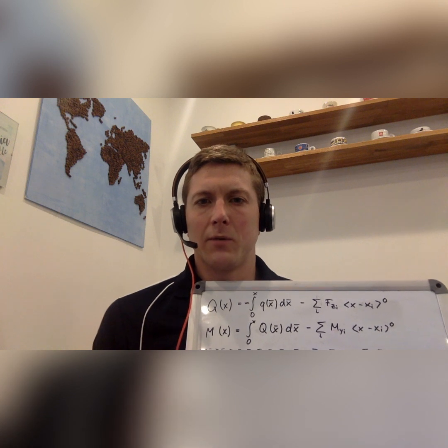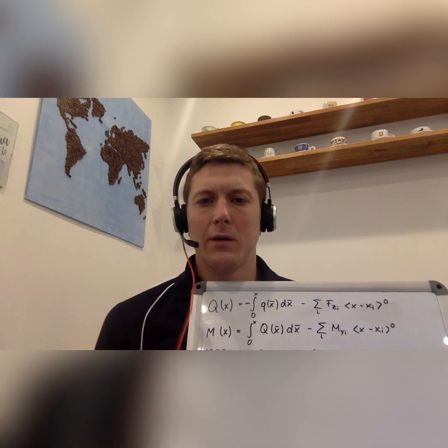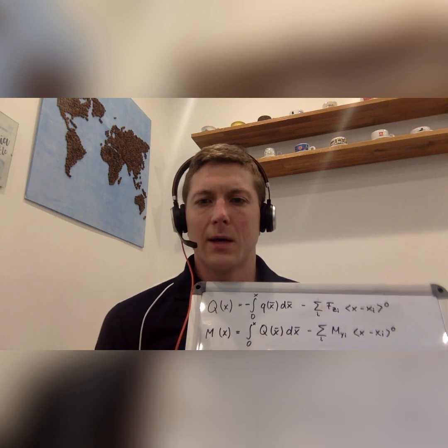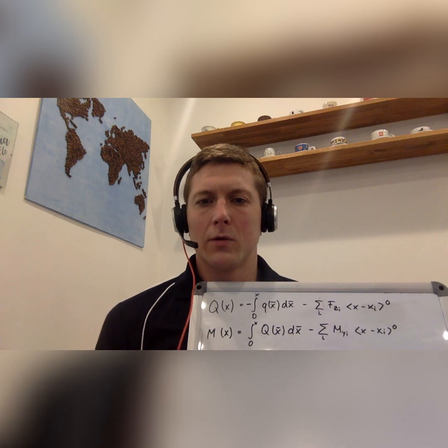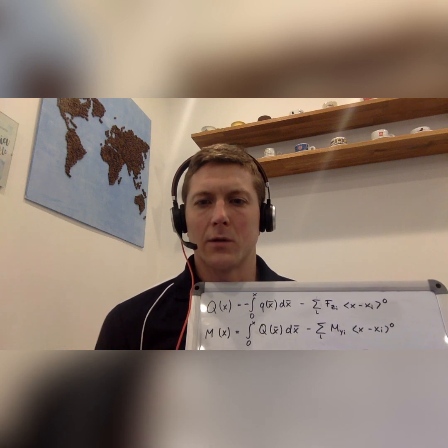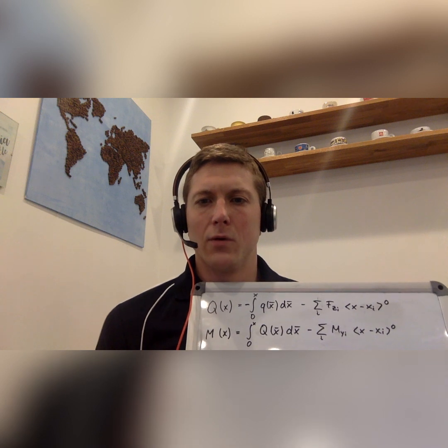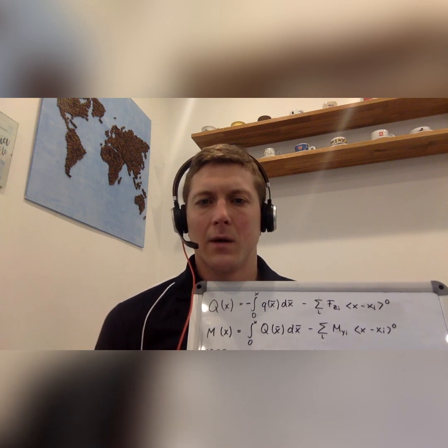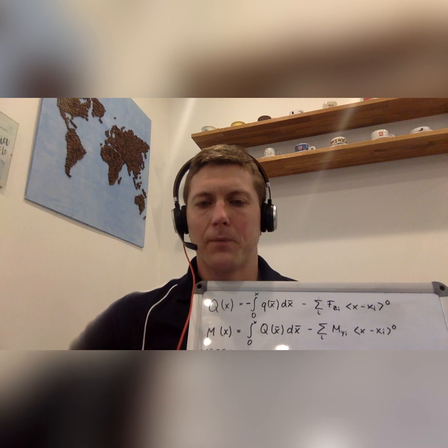And then you would have, of course, the same way to calculate the shear force and the bending moment. So there are two different possibilities, either the definite integration scheme, which is given here. That is the reason why I use this x bar instead of x for the integration variable, or you could choose an indefinite integration, so without the start point and the end point of your integral, so just without the 0 and x, and then write q of x dx instead of q of x bar dx bar. It's up to you.